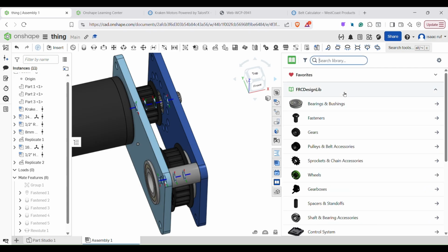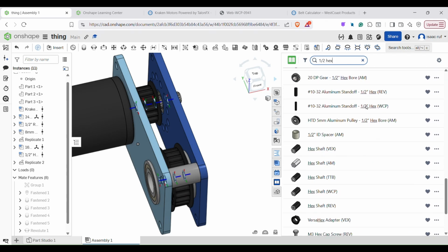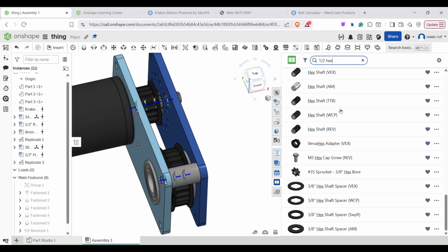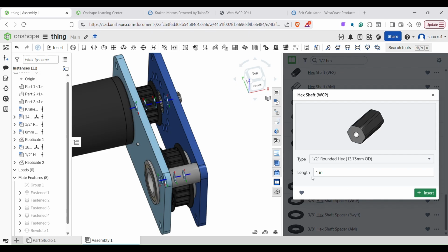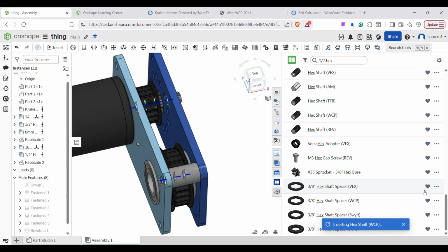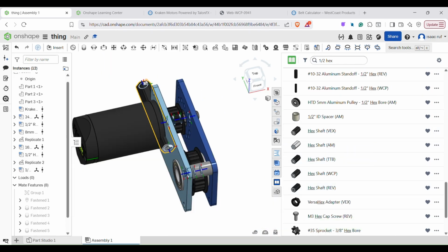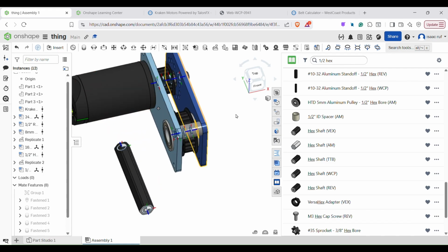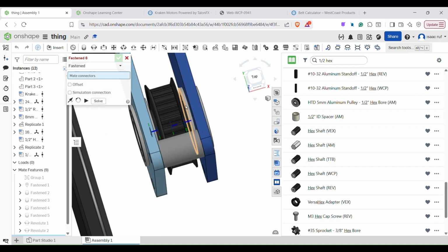So let's go to inch. Next. I will say this new library they have is way better than what we used to use. It's exponentially better. We'll just make it like 3 inches long. That'll be good. Yeah. Insert. This is Thunder Hex, by the way, not Hex Shaft. Just so you know. There's a slight difference, but it doesn't really matter all that much.